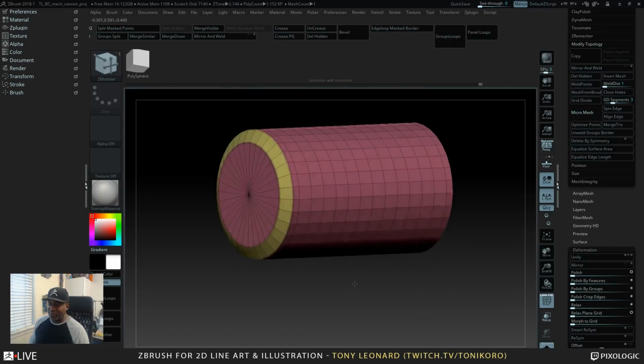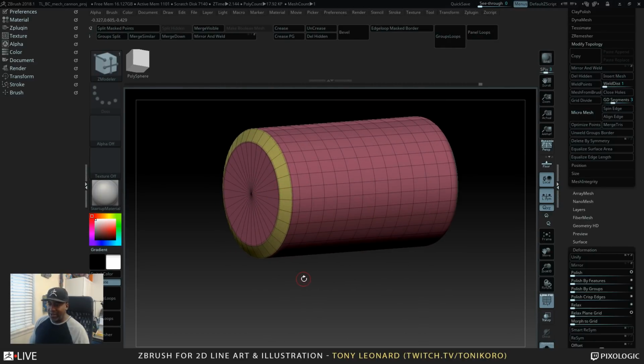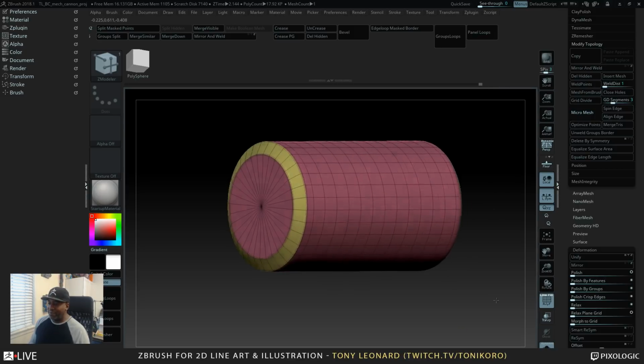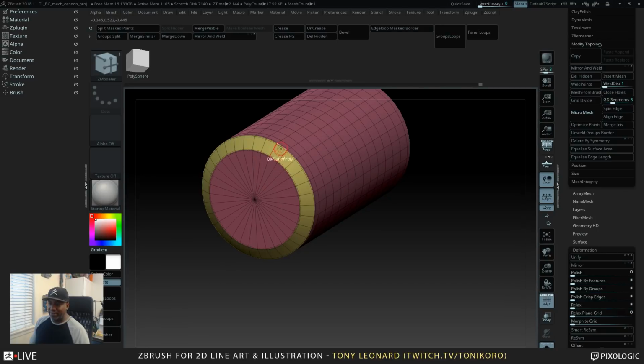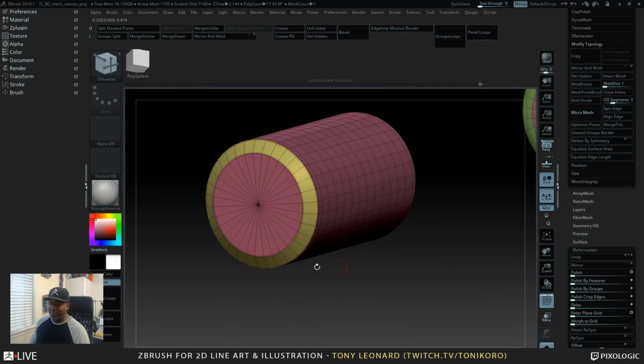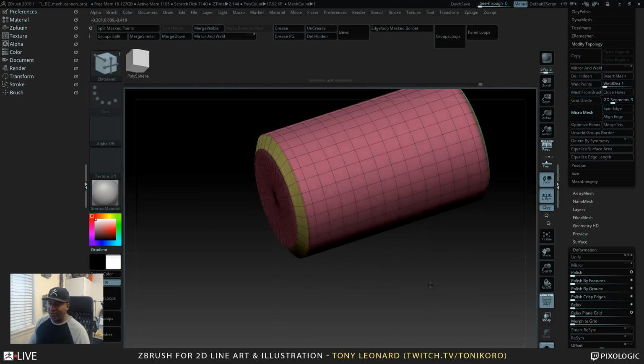So just as a rule, if you put a crease there and I subdivide it, you see how this edge is rounded because it has no supporting edge loop to keep the shape of the edge of the cylinder, and it has no creasing so that it actually marks it as sharp. So what I'll do is come through and start putting in the creasing that holds edges, and then I can move these out, or maybe do some extrudes with the world space widget and push some of this geometry inwards.